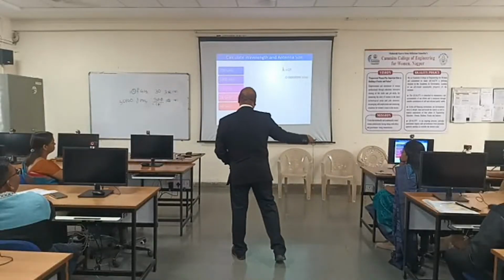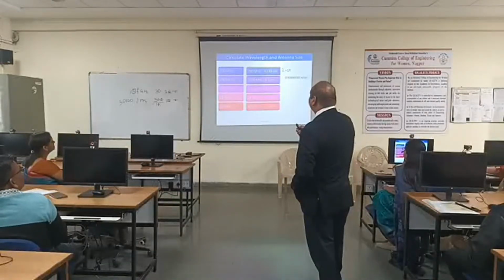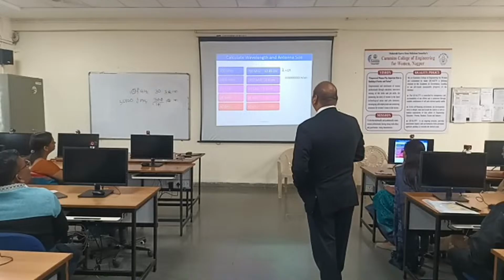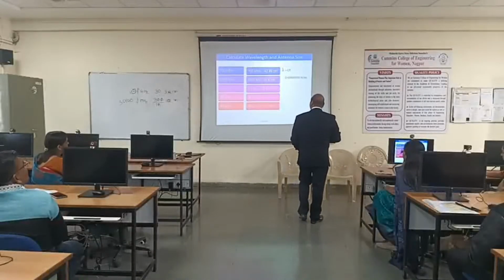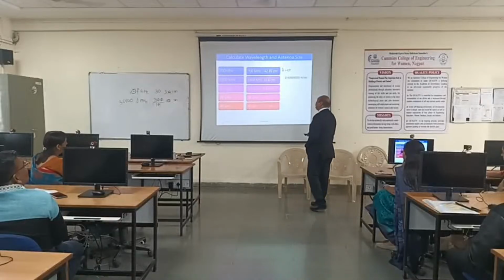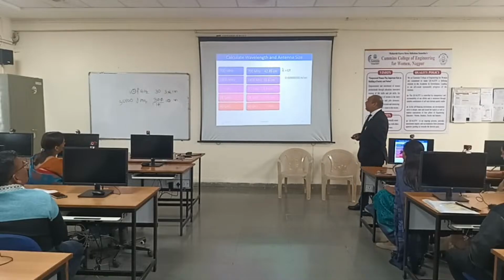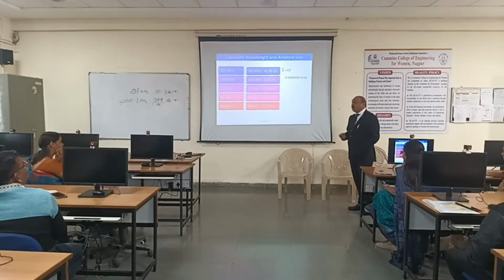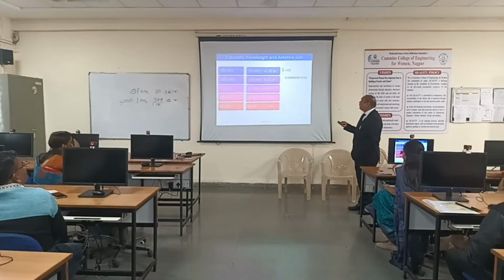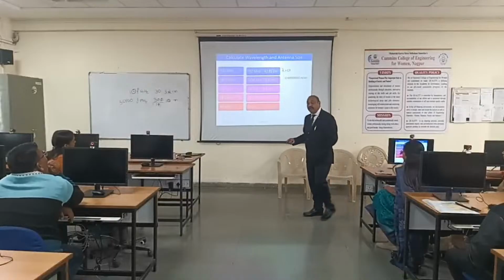So if you want to go for this, for example, let us say for 700 megahertz, the wavelength is 42.85 centimeter if you calculate. If it is 1800 megahertz, the answer is 16.6 centimeter. For 3.5 gigahertz, it is 8.6. For 28 gigahertz, 1.07 centimeter, and for 40 gigahertz, it is 7.5 mm. So we start with centimeter and go down to mm wavelength for 40 gigahertz.